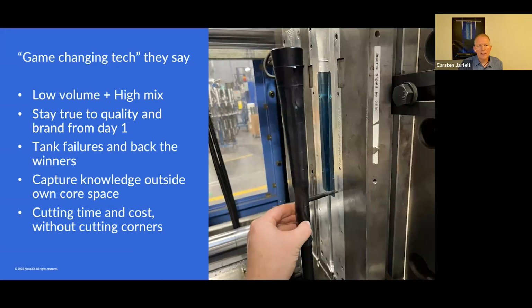And I think what is interesting with this one is that it's printed on an NXE 400 in xMOLD, and those 6 tools consisting of 12 tool parts were all done in 9 hours. So in 9 hours, you have 6 complete tools, and we were hoping and believing that they would yield a bat each. But what Wilson actually discovered was they could get between 4 and 6 bats per molding tool set. So right there, 9 hours in printing and some cleaning and curing, then you now have the ability to do tools overnight, so you can do around 25 bats the next day.